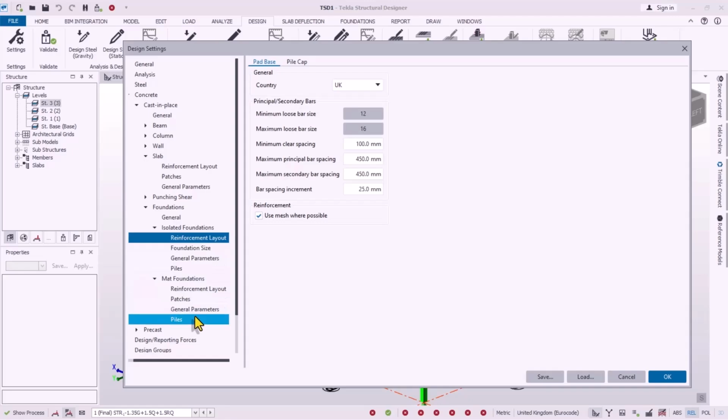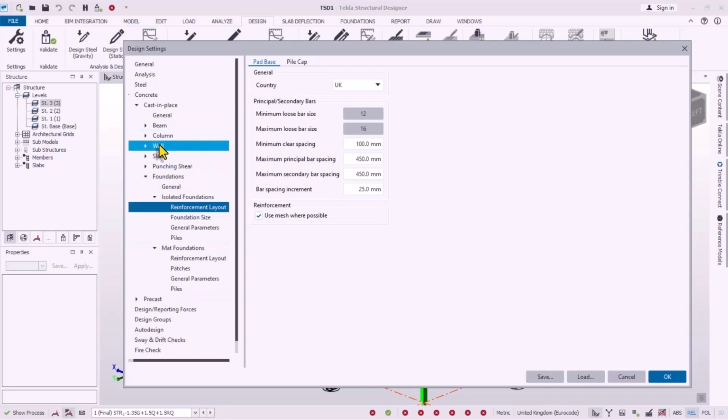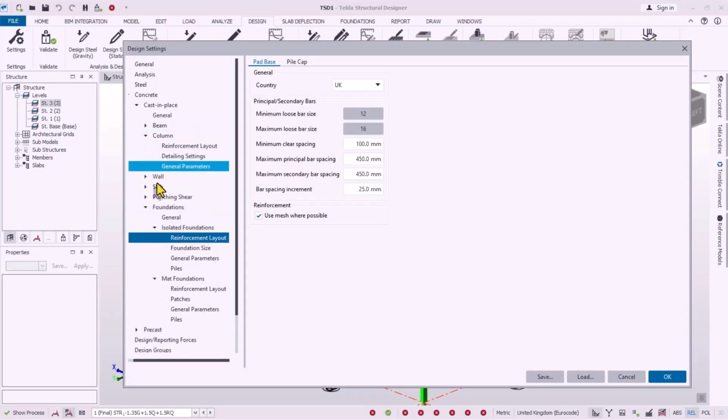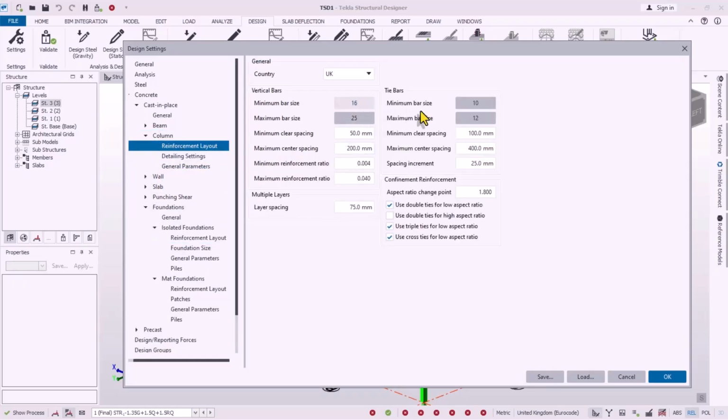Okay, so for every other setting here, we're not designing piles for now. We don't have walls in this structure. We have reinforced concrete columns. Select in that provisions. Okay, so you can see the minimum bar and the minimum bar size is 10. So you see we go by this minimum and this maximum successfully.